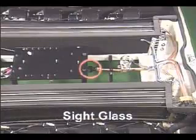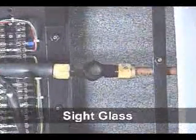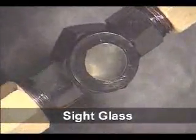A sight glass is installed inside the evaporator unit. It can be checked from inside the bus. It's very useful when checking the amount of refrigerant.